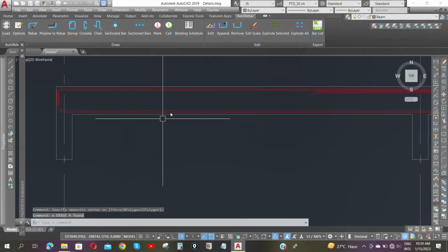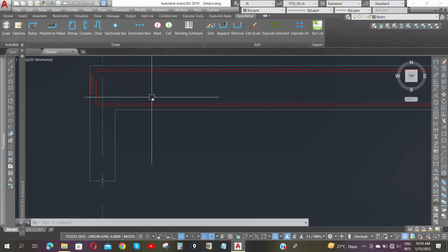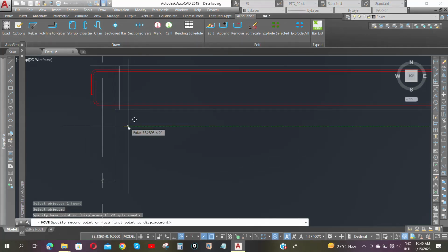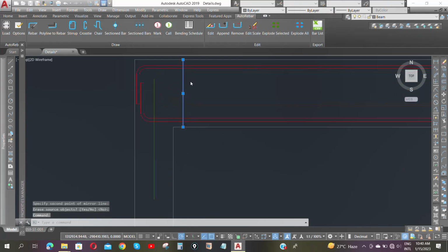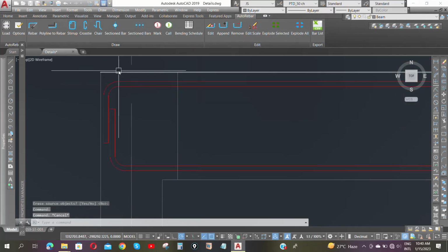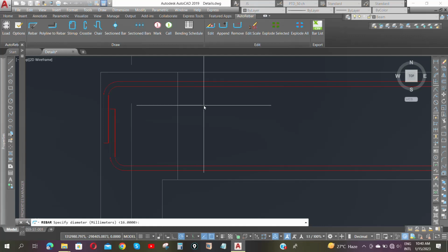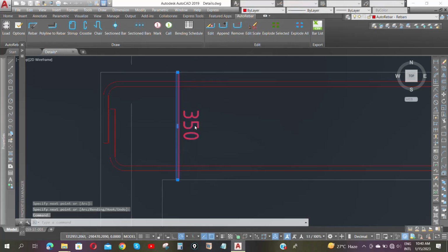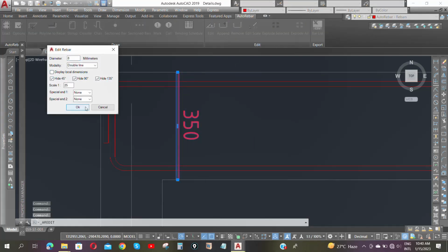Okay. So my links, now I will position my links. So my links should start 50 mm from the face of the column. So this is not a polyline. So what I'll do, just come here. I want to use its bar. I'll type in the 8 there. So I can remove this, don't need this.